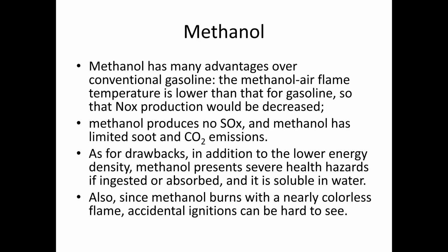As for drawbacks, in addition to the lower energy density we talked about earlier in regards to the methanol mileage compared to gas mileage, methanol produces severe health hazards when ingested or absorbed, and it is also soluble in water. Also, since methanol burns with a nearly colorless flame, accidental emissions can be very difficult to see.